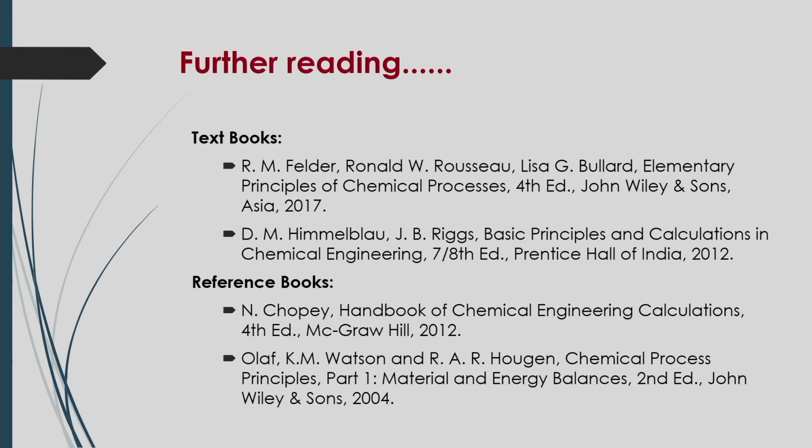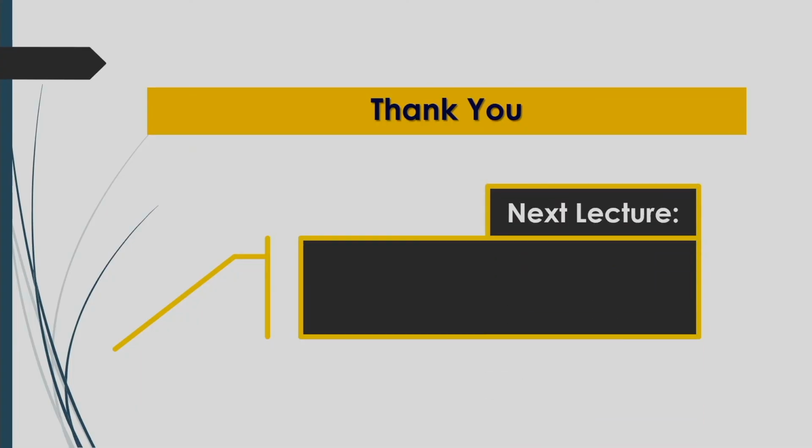So, we have discussed these process variables of pressure and temperature in this lecture, and how to estimate or calculate pressure from the basic fluid static equation, and how to derive it. I think it will be helpful for your further understanding of the calculation of the process, and you have to remember certain things of the hydrostatic equation, and also how to use it to calculate pressure with the manometer.